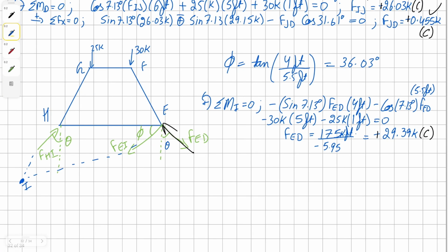Now we can, like before, take moment about the point E. We're going to have just the vertical component of force HI. It's 5.5 feet away.